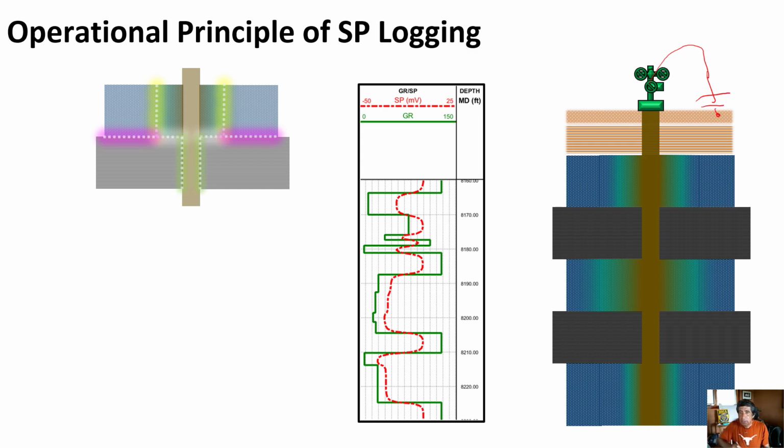The connection where we ground it has to be electrically quiet. We don't want a situation where the electric fields near the grounded electrode might change over time because of a generator, because some other activity happened near the electrode will modify the measurements.